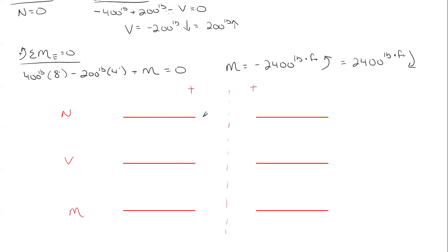So normal force will be if it is pulling on that cut line, which technically, if you want me to write it, I could write it right there so we can get rid of this so it's a little less confusing. So if it is pulling on your cut, that is positive. That is positive tension. For shear, if it is downward on the right end of the left segment, that's positive.